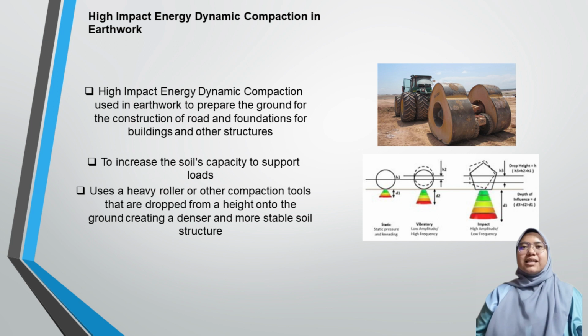site. Next, high-impact energy dynamic compaction in earthwork. This technology is used in earthwork to prepare the ground for construction, especially for roads and foundations for buildings and structures. It uses heavy compaction tools that are dropped from a height onto the ground, creating a denser and